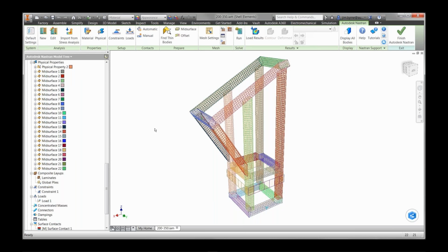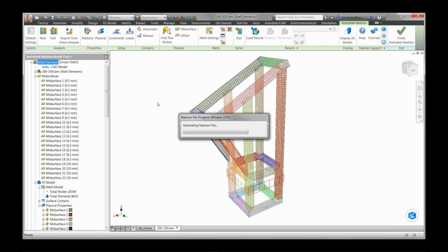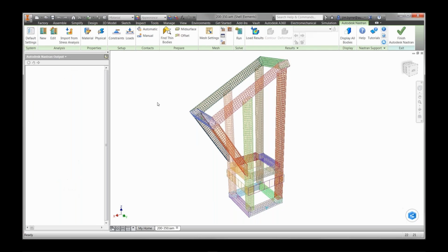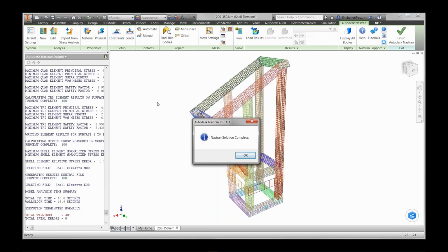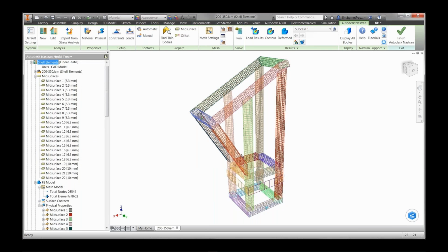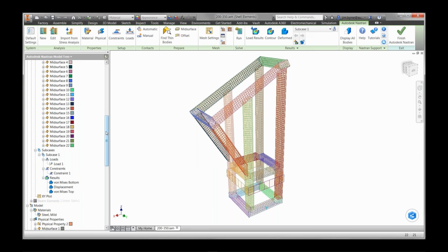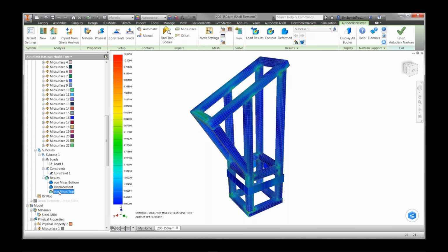So ease of use is the best way to get started faster and reduce your learning curve. And it solves very quickly. As you know, Nastran is known for its fast solving. We quickly have the results for the one mesh: onto the top side of the shell, it shows a value of around 10.6, and onto the other side of the shell it is 12.1.